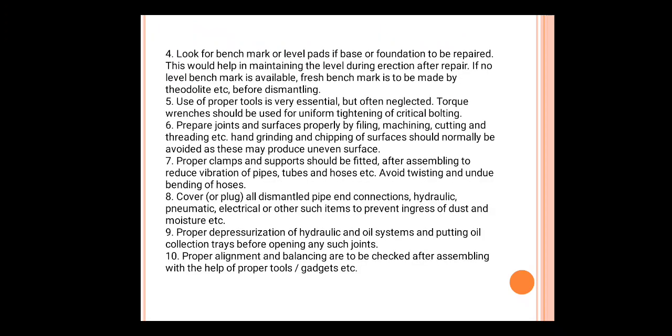Fourth, look for a benchmark or level pads if the base or foundation is to be repaired. This helps in maintaining the level during erection after repair work. If no level benchmark is available, a fresh benchmark is to be made before dismantling.